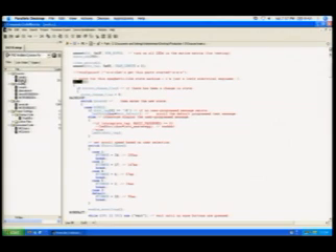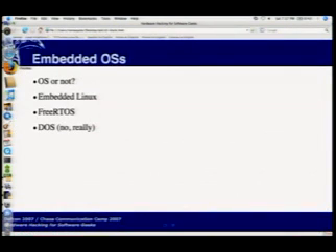The downside of not having an operating system is, of course, that you have to do all the hardware access yourself. However, if the processor is simple enough that you can't put an OS on it, there's not going to be a lot of hardware to be accessing. It's generally the AVR chips that I'm most familiar with. Doing SPI communications is a simple matter of setting a few registers and then loading one variable with what you want sent out the SPI port, and then checking a few milliseconds later to see what came back in.